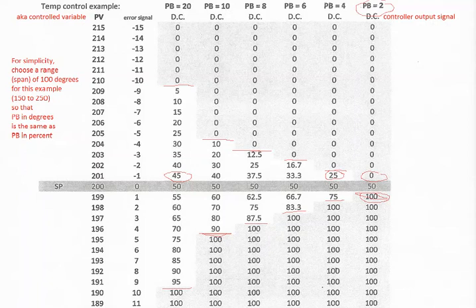That's valuable information. And one simplistic way of tuning would be to crank up the gain till it oscillates and then back off just under that point. That way you kind of have the best of both worlds. You have the tightest control without going into oscillation. So your proportional band is as narrow as it can be.